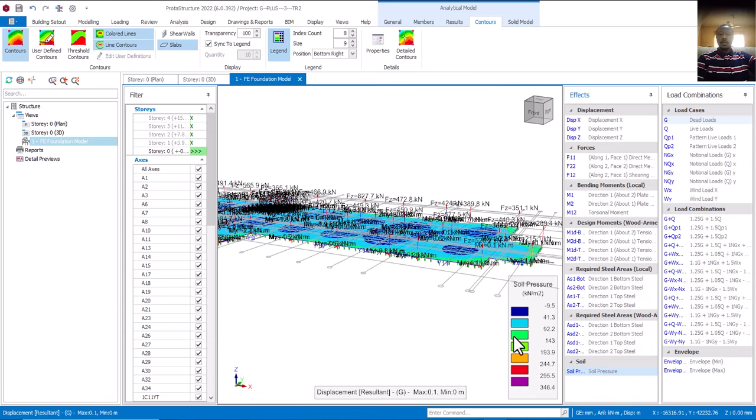That will be in our next video. Is that okay? But for now, let's check our slab. Because it's expected that your value of the soil bearing capacity should be more than the structural pressure, which is this one. Is that okay? You can say our structural pressure is 346.4, and that of the foundation is 150, isn't it? So how do you now solve this issue?